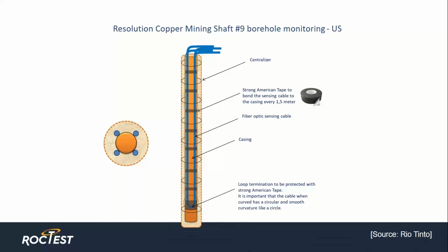The fiber optic cables were installed to measure strain and temperature along the length of boreholes and be read regularly after installation and during the drilling of the shaft. 2 cables are installed in a loop configuration looping up around the bottom of the borehole. They are taped to the casing as the borehole progresses to its final depth. This method allows for redundancy in the reading. The mining operator typically interrogates the fiber optic cables to collect baseline data prior to mining.